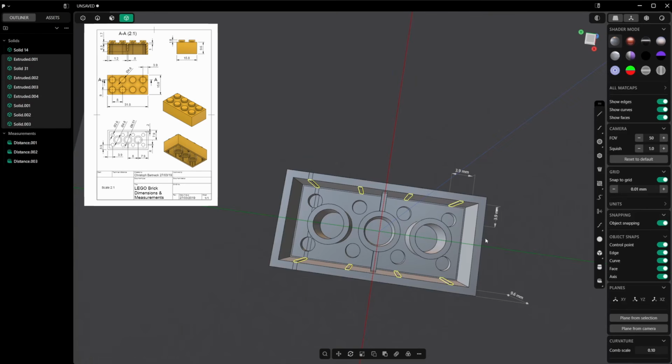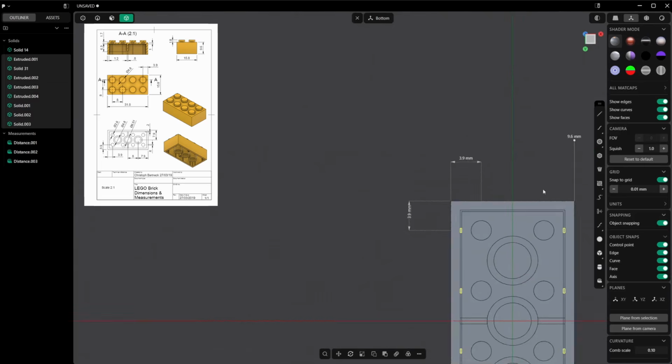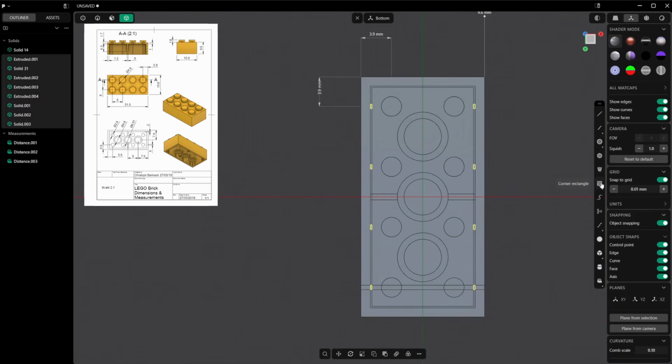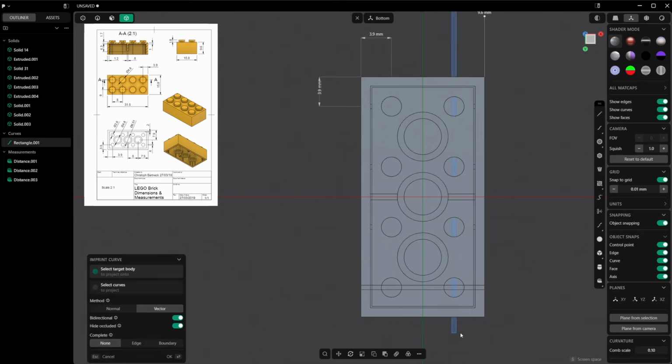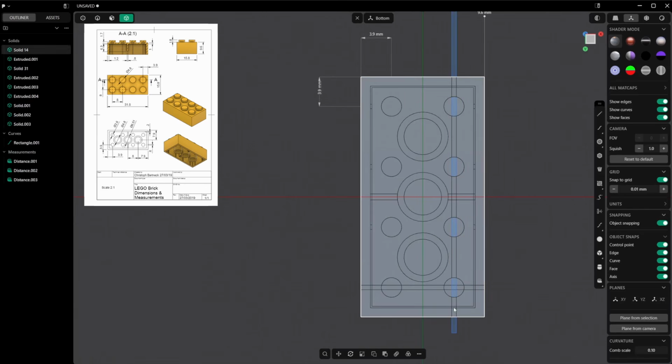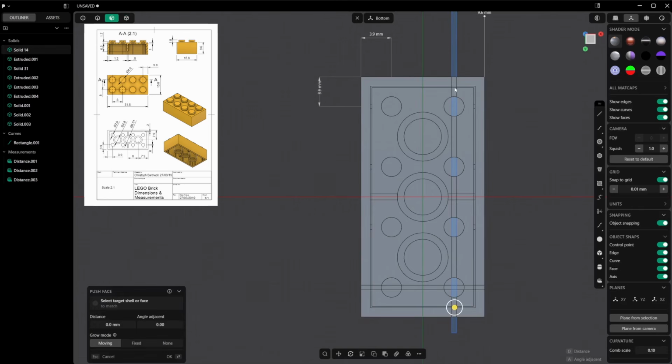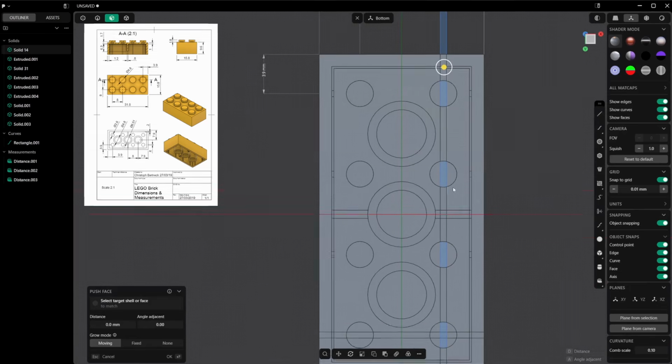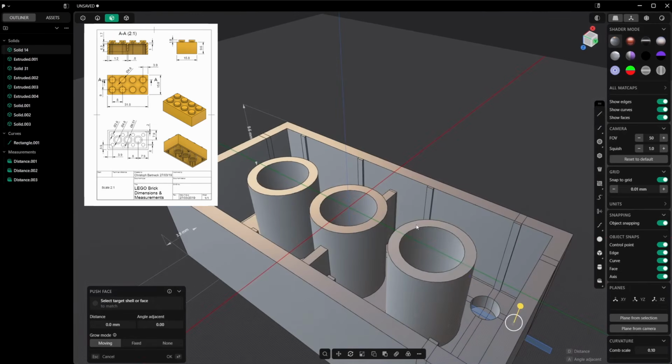And to make the other ones, I'm going to do exactly the same thing. So I could duplicate these, but I think I'm going to be faster if I just select one of these, C to center, tab to set the size, which is 0.6, enter, Shift I, imprint, disable hide occluded, OK. I'm going to select 3 for faces, this face and this face. So making sure both are selected.